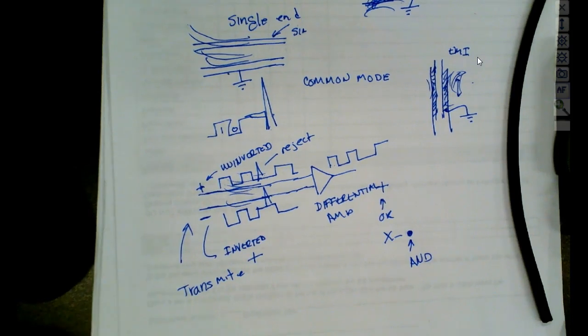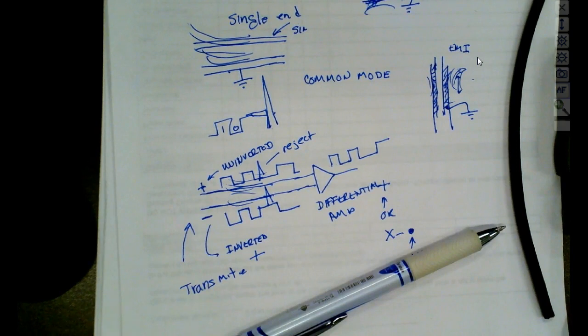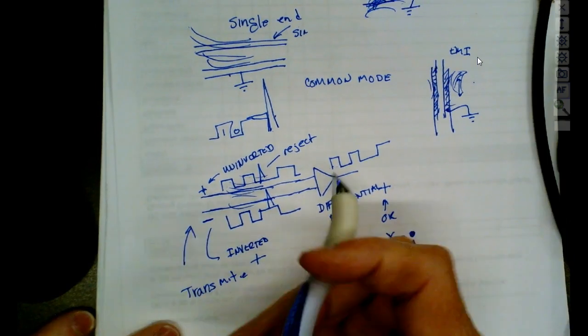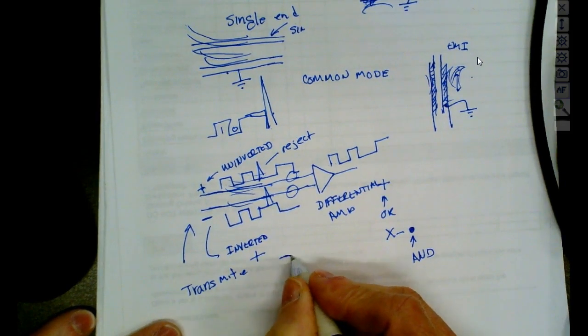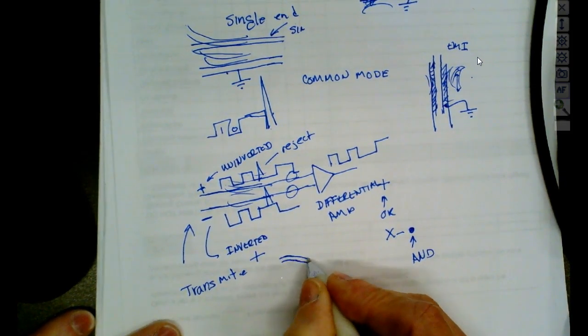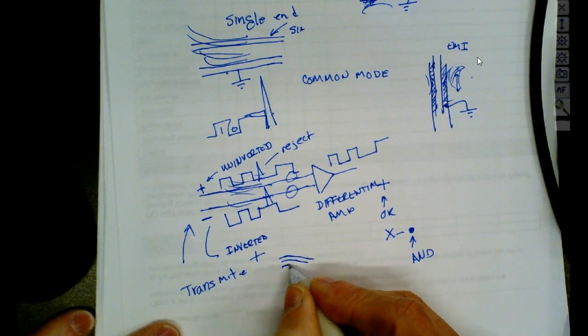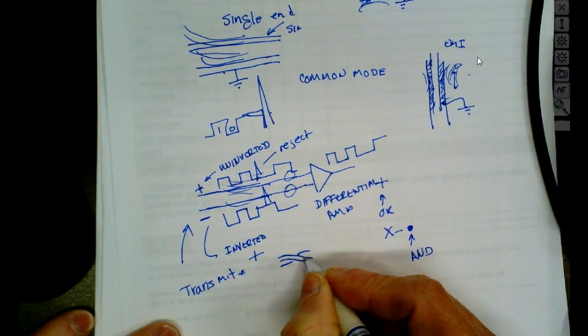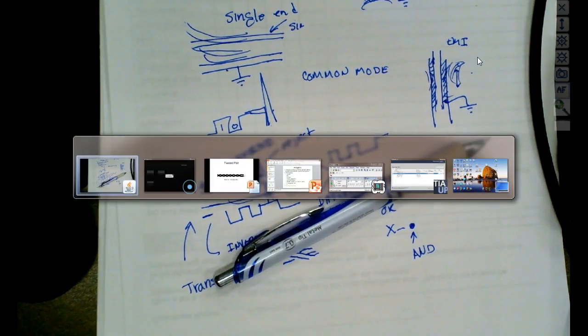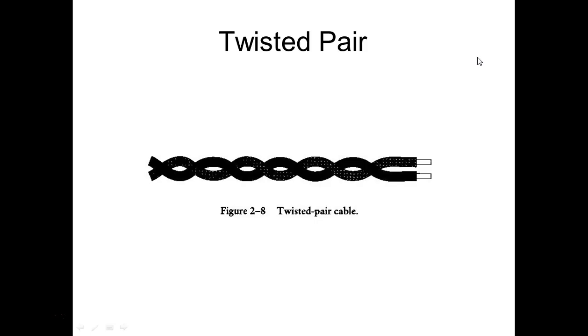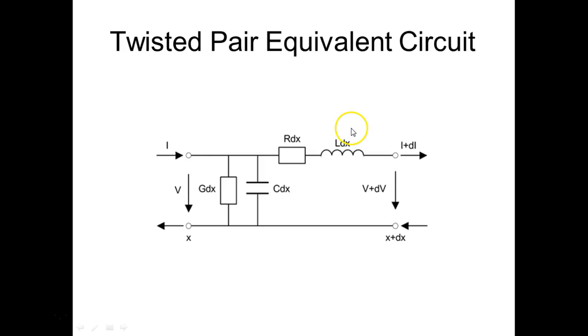So what they do in networking is, we still need to have characteristic impedance if I'm going to get impedance matching. So what they use is twisted pair cables. So what we have is two wires, and why we call them twisted pair is exactly this. They go in pairs. So this would be an example of a twisted pair cable. Now, literally, these guys are twisted together, and you don't really have any doubt.